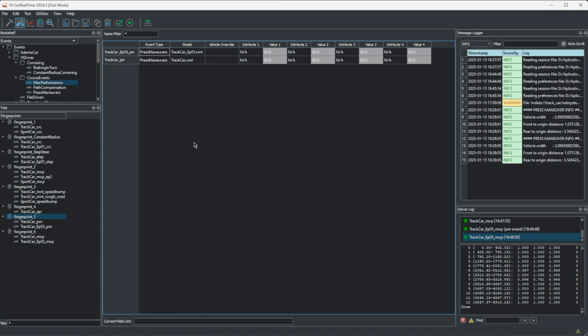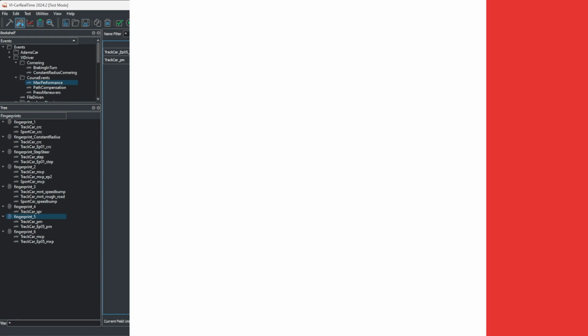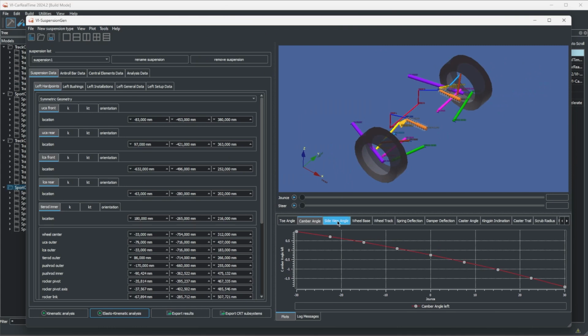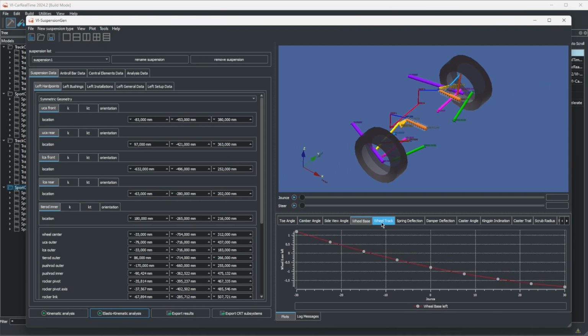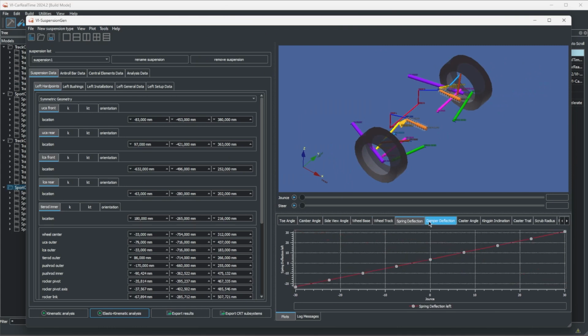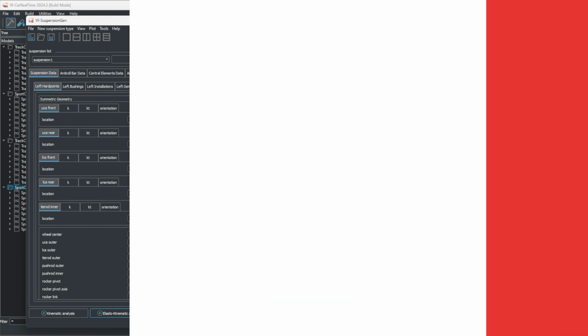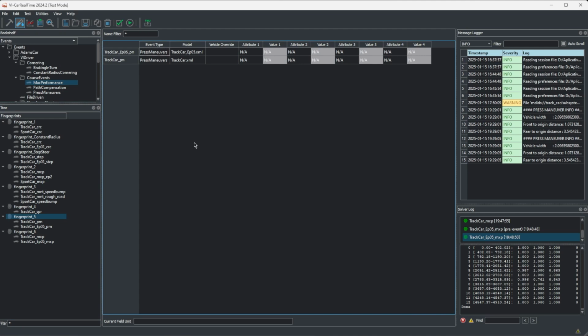As an example, moving an outer hardpoint a little farther out may influence the motion ratio, inducing a change in overall balance too. The tools we use today are ideal for this type of development since they provide us with a comprehensive view of how the car responds to such changes. When combined with the many resources we've been using throughout this series, it lets us analyze and develop virtually all aspects of vehicle dynamics in a safe and efficient environment.